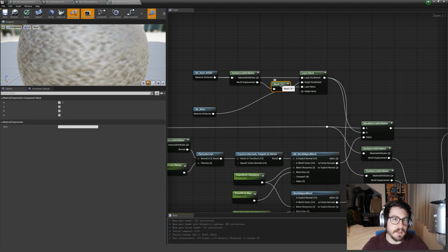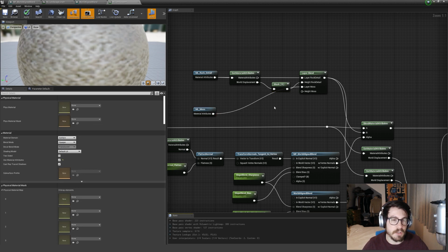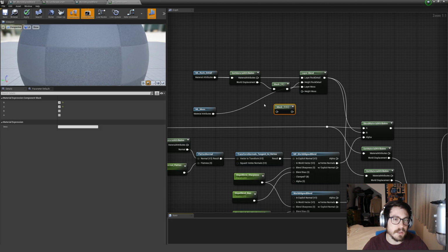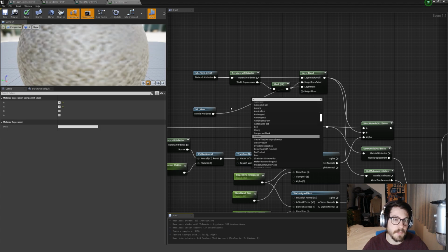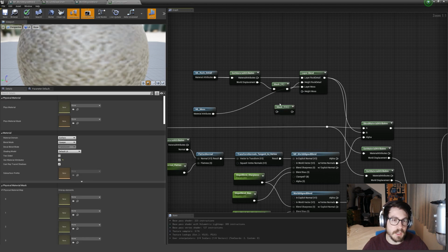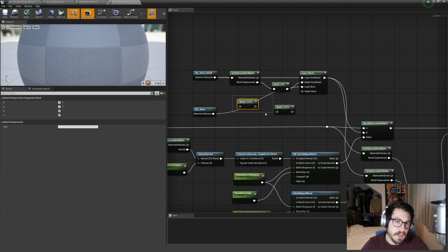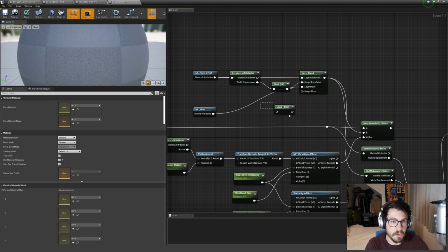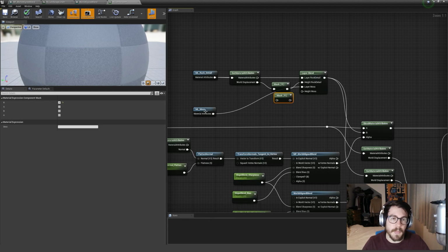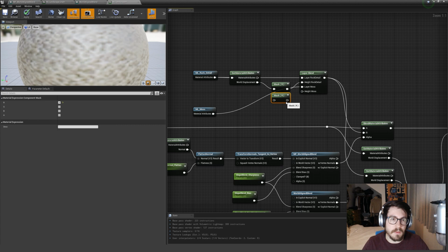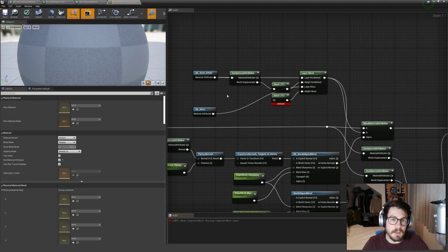And to get this mask, by the way, you would just hit Shift and C, and Shift C gives you this parameter here. That's a component mask parameter. This also is that one if you would want to search for it. So we add this in here.